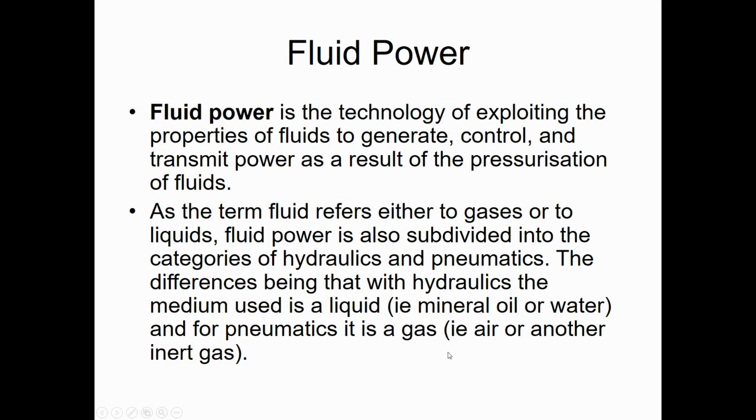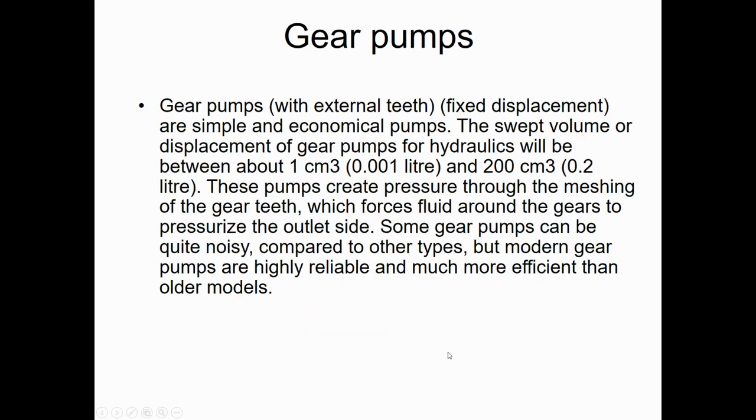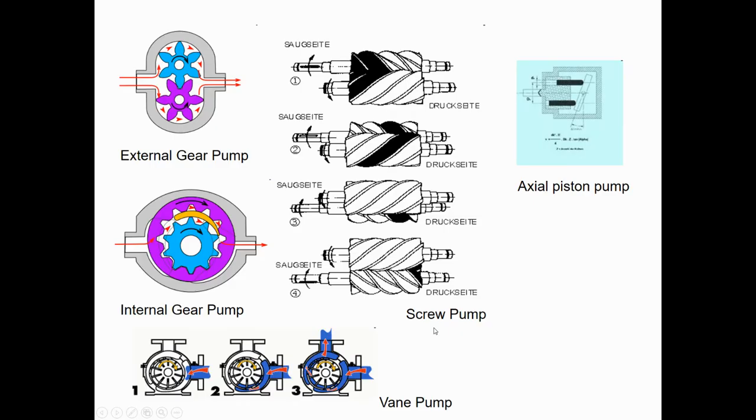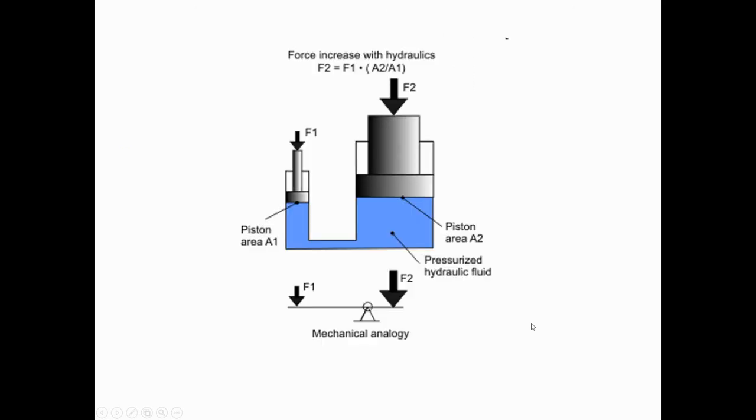So fluid power is a very simple term. Now that's what we're talking about. The process is very simple. If I put pressure by using this piston on this area, which is going to be equal to 100 kilopascal, the pressure at any point in this fluid is going to be the same.